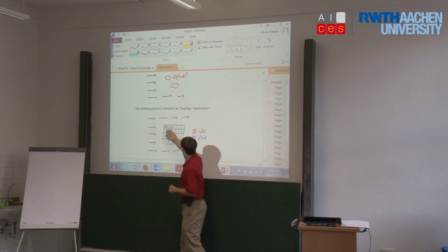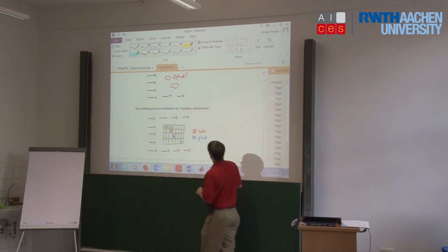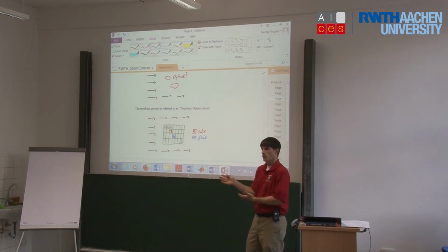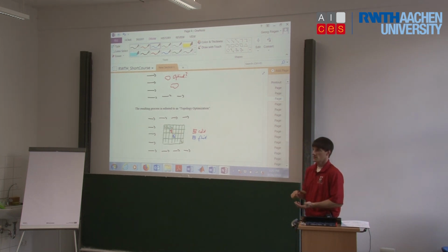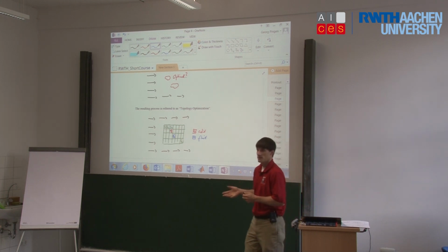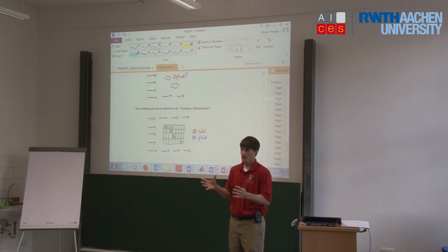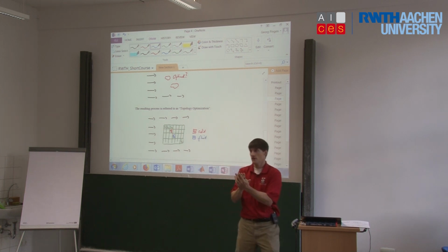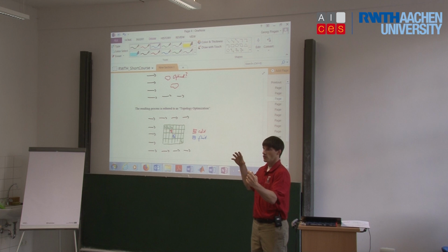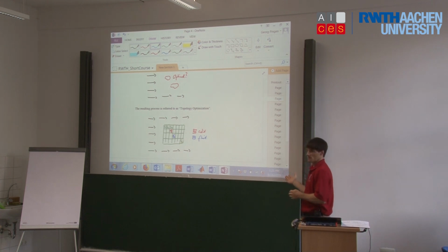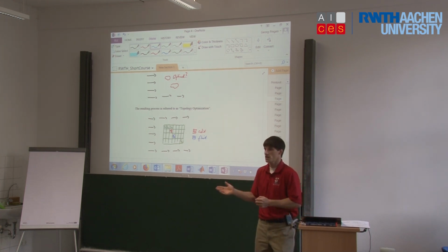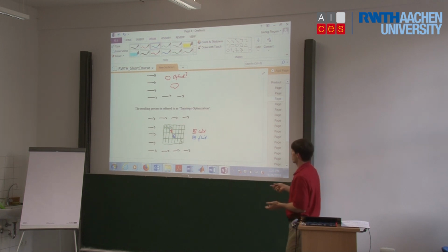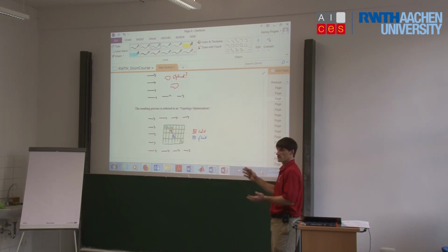And so now we have all these design variables, and they can all change from being solid to fluid, and we can do this continuously, so it's not either all solid or all fluid, it could be something in between, and that something in between might be porosity. So let's say we use a sponge, and every point here can be a sponge, and that sponge can either have big holes and not be there, or it can have smaller and smaller holes where at some point it becomes a solid. And so mathematically that will allow us to continuously change any point in our fluid from a fluid to a solid, or back from a solid to a fluid.